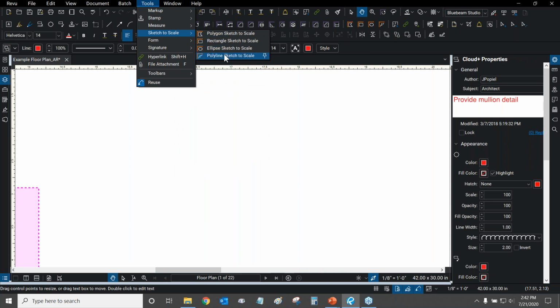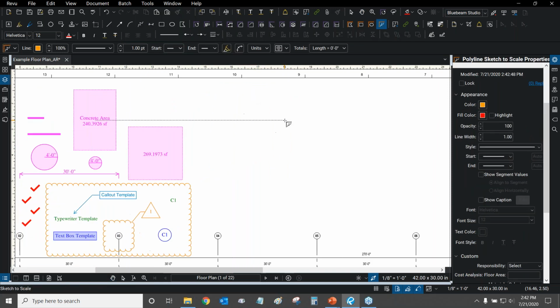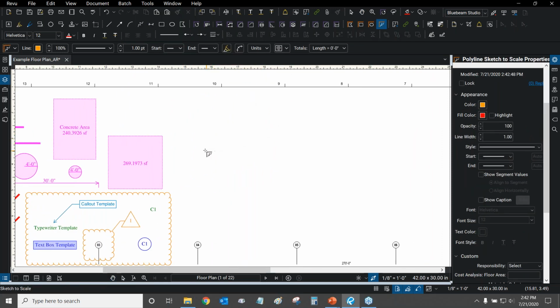And let's do the last one, polyline, very similar to polygon, but of course it's not going to fill itself in and it will measure length. Let me turn off my snap to markup again. So I can click once, specify the length. So let's go 5 feet at -45. Oops, I have to press tab first. So tab, -45, enter. Next, I want to go 10 feet to the right, which just means 0-degree rotation.